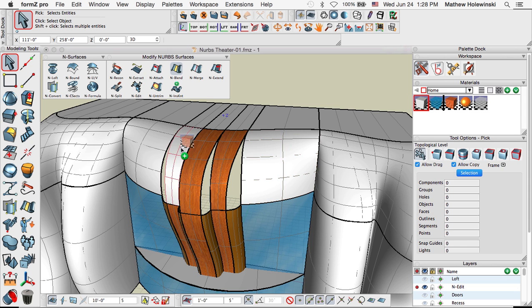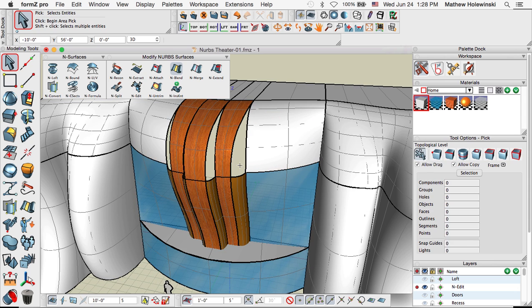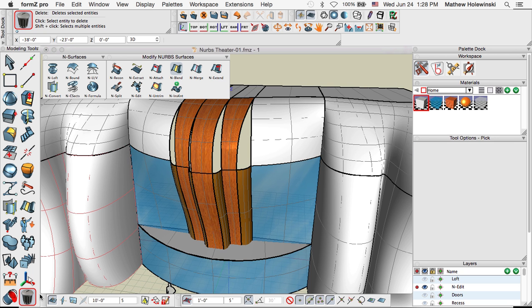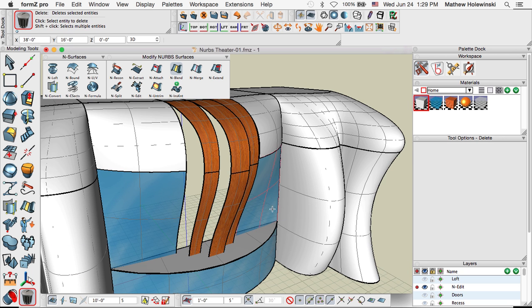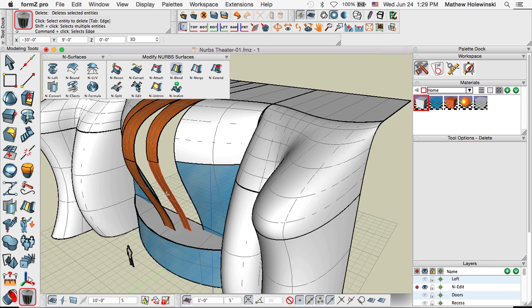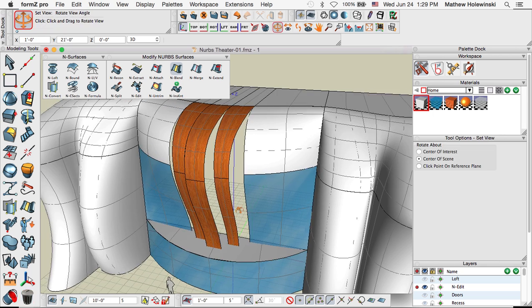And we have 2 different pieces here because we've actually blended. The blend tool is creating a brand new blended surface. And so if I were to delete these objects out of the way here, it's fine to keep those as separate pieces. Everything's blended nice and smooth. But if we want to merge those together, we can do that.